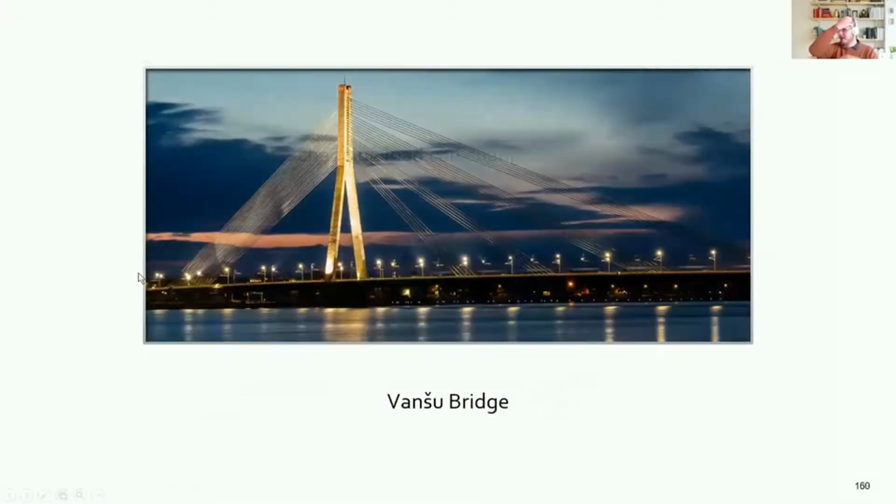And for example, here is the, let's get the pronunciation right, Vanshu. I hope that's close enough to the correct pronunciation. So this is a non-linear structure, and we have these cables in tension. If the loads were to be reversed, let's say you had sufficient wind uplift to overcome the self weight of the deck, that could put the cables into compression, which will buckle the cables and everything.